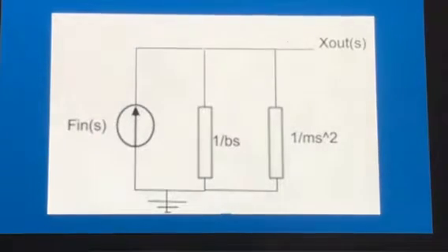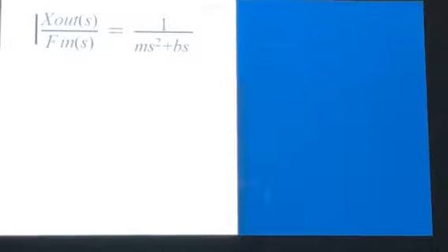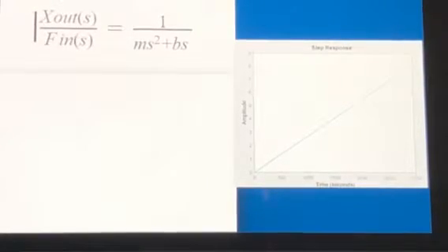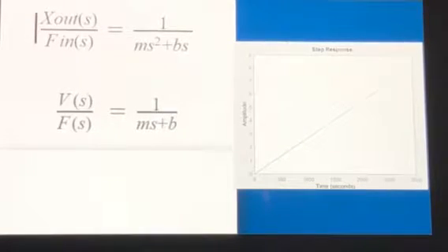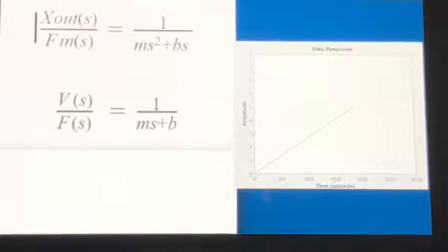We can then represent this system as a current source and 2 resistors that can be used to determine the transfer function. With the model for the system considered, we built the transfer function at that point of the position considering force. And with this in mind, we were then able to take it and derive it, giving us a V(s) over F(s). This system then allows us to find velocity from force transfer function.